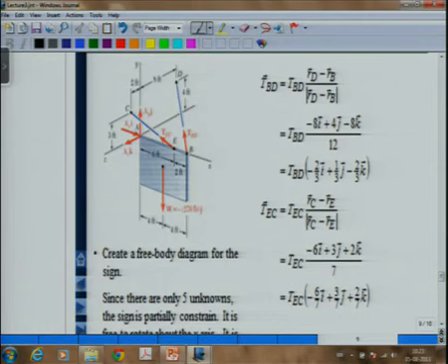Next we have to talk of the tensions which are there. There are 2 strings which are there. So, there is a tension going from E to C and tension going from B to D. Now, the scalar value is the tension. Do we know the direction of the tension in EC and the direction of the tension in BD? We do know, because from the geometry we know the geometry about EC, the geometry about BD. So, therefore, we can work out the directions of the 2 tensions.